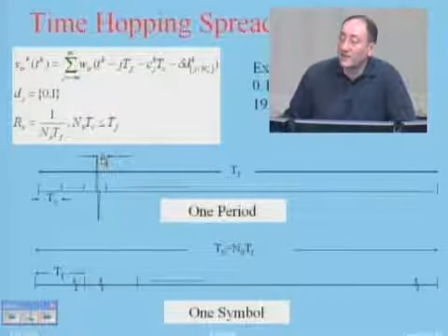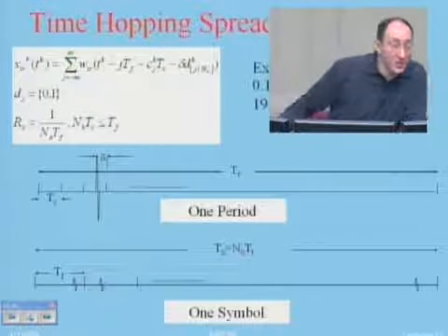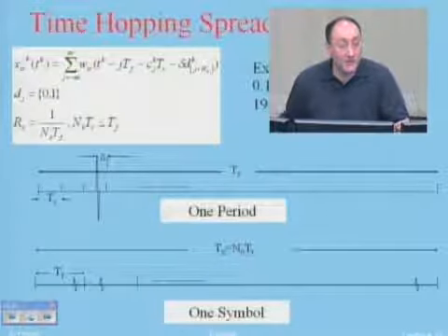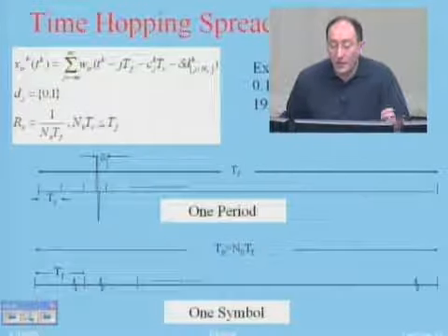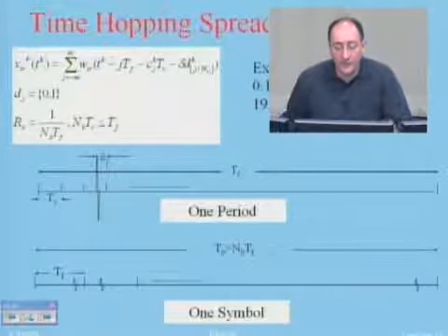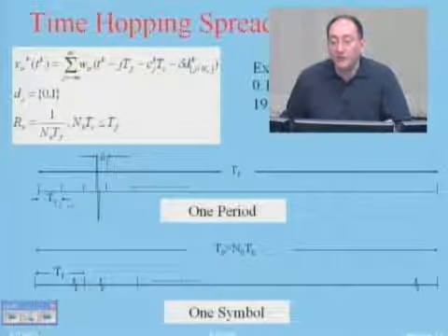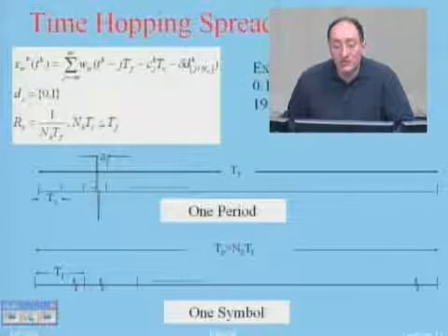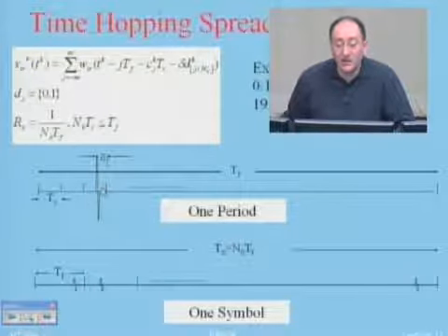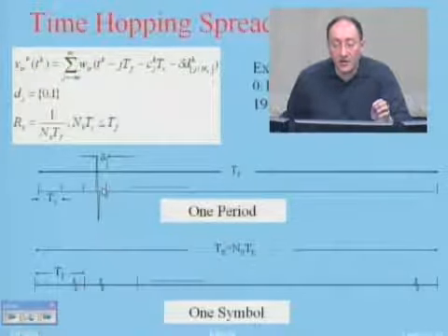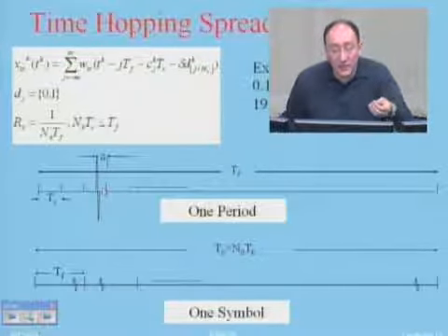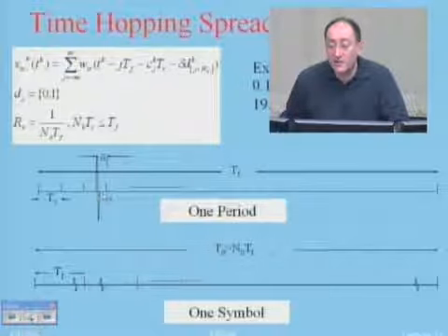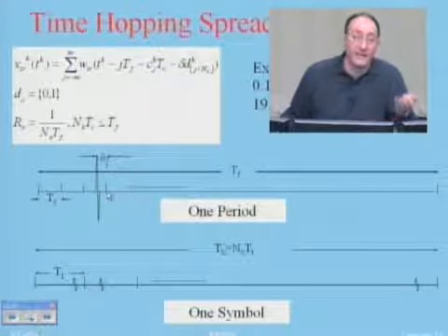Okay? So, in a sense, it's also pulse position modulation for differentiating between zeros and ones. Okay? So, I want to send a chip. I find the number of the chip, I come to that time slot, and in that time slot, if in that particular chip I was sending an information bit which was 1, I put one delay, and if it was information 0, I put another delay.